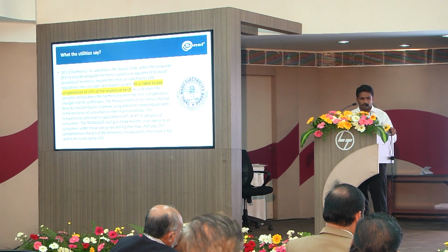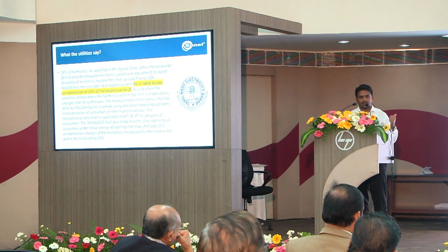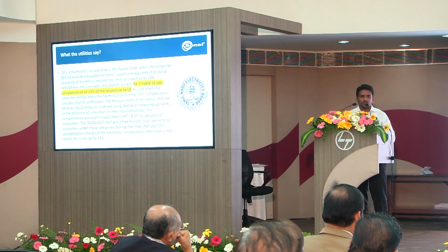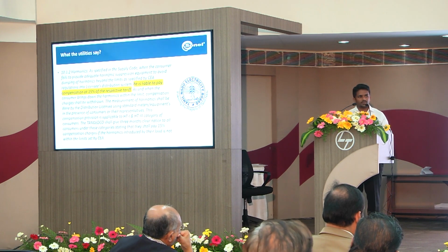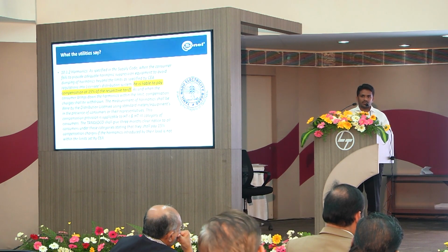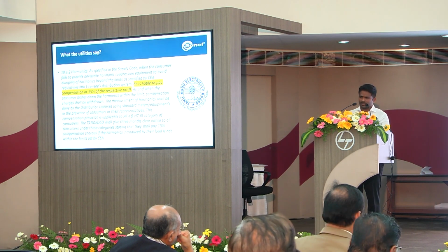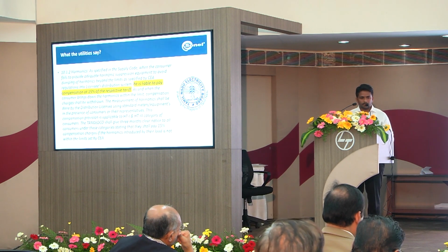It's clear. But when you come into the tariff amendment of TNEB, this is an extract from the tariff of TNEB. If you do not maintain your harmonics, you have a 15% penalty. Please note this can vary from state to state. In Maharashtra, the scenario is different. In the states where kVAH billing is applied, it is completely different from the other states. Also, it can completely vary from state to state. In TNEB, there is a 15% penalty.